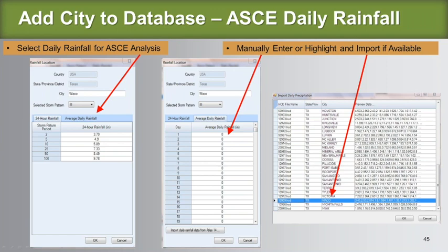So recently, a couple of weeks ago, we made changes to this, and there's a series of database files of rainfall based on the U.S. long-term, or the U.S. and Canadian long-term pavement performance study. And so we've imported a spreadsheet that has all of the rainfall data, typical average yearly rainfall. And so you can actually go, it will open when it says in the bottom, import daily rainfall, you click on it, it brings up Texas, and instead of having 5, 6, 7, 10 cities for Texas, it's going to give you 50 to 100.